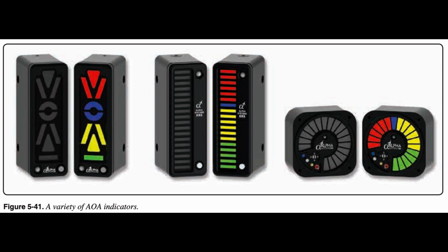More than 25% of general aviation fatal accidents occur during the maneuvering phase of flight. Of those accidents, half involve stall/spin scenarios. Technology such as AOA indicators can have a tremendous impact on reversing this trend and are increasingly affordable for general aviation airplanes. The purpose of an AOA indicator is to give the pilot better situation awareness pertaining to the aerodynamic health of the airfoil.